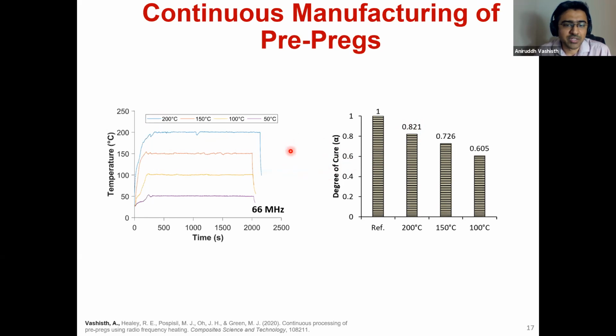And just to remind you, I think I forgot to mention this. This was a bifunctional epoxide that was cured with DETDA resin. So these are usually cooked at 121 degrees Celsius to 177 degrees Celsius. So that's kind of the range that you cook these epoxies in.